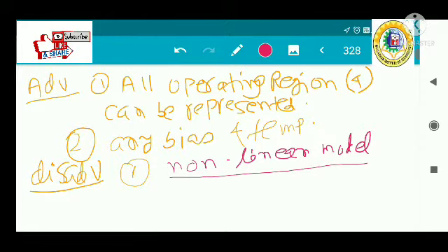Whenever you read out the different network theorems, the first line says that the theorem is valid for any linear bilateral network. As long as the circuit is represented by linear circuit elements, you can apply the superposition principle or other network theorems and simplify the circuit. But here, as this is a nonlinear model, you cannot apply the linear circuit theorems. So that is the main disadvantage.